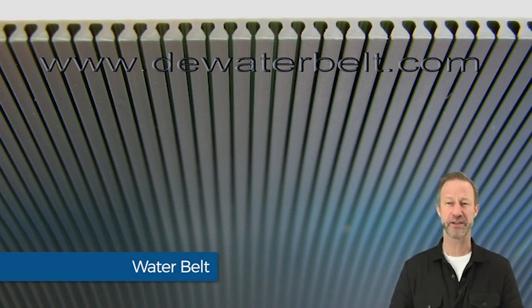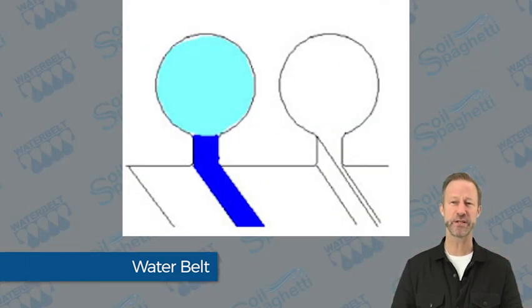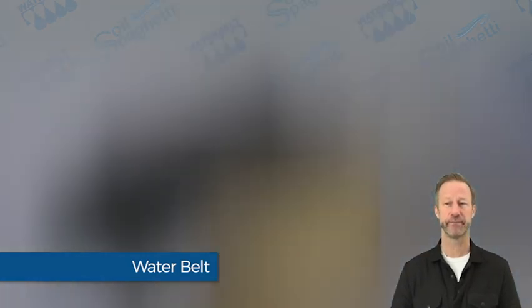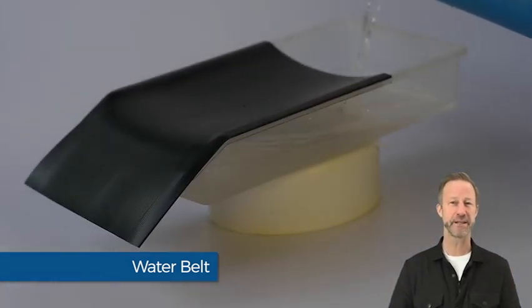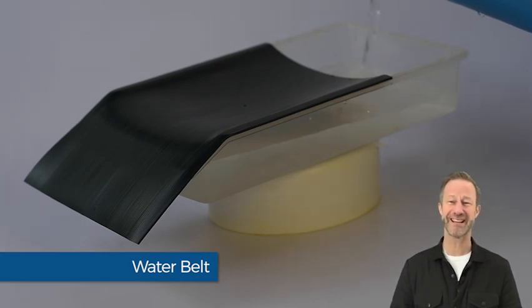The micro channels are accessed by continuous slots running the entire length of the belt, and water entering through the slots is held in the micro channels by capillary. Once water fills the micro channels, it flows through the channels to be discharged. As the water is discharged, a siphoning action also pulls additional water into the channels.